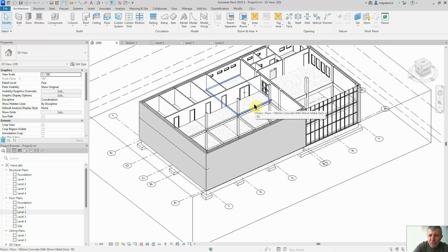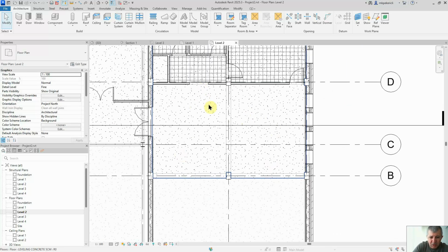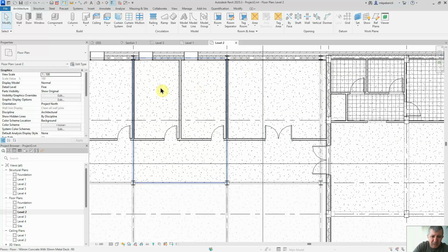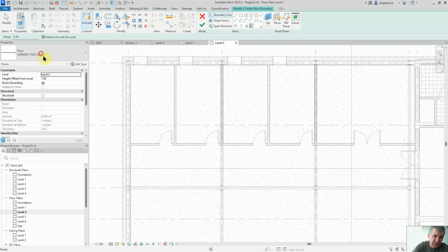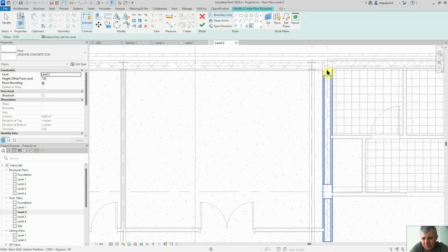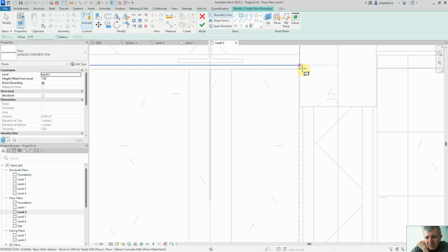What I will continue to do is place the floors now. Wet spaces should be ceramic tiles, but for the rooms I'm going to use carpet. So these rooms will all be carpeted, but this corridor and these will be ceramic tiles. What we need to do first is floor, architectural floor, but level concrete. First, the level concrete here will be, well, I can do it roughly